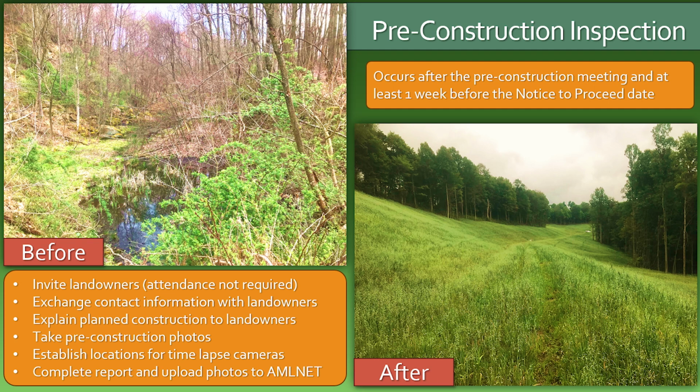This inspection should document any existing site conditions or any changes to the project area since the pre-bid conference. It should note any utilities or potential hazards not identified on the design plans, establish locations for the placement of time-lapse cameras, and take pre-construction photos. It is important to understand the reclamation goals for the project. Pictures should convey all the work completed. These photos will be used for both promotional and educational presentations when the reclamation is completed.